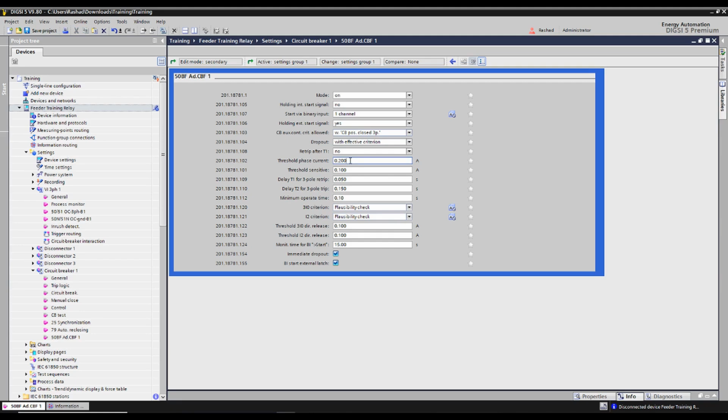I will tell you about something I decided before, a case that might be present, for example, in the switchgear transformer incomer. If this transformer has a star, and this star is grounded via NGR at 13.8, for example, here, when faults occur, these faults might have a limited current. So in a case like this, even if the fault is on a bus bar, its power supply is limited by this transformer because of the NGR.